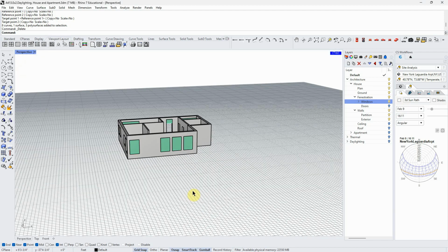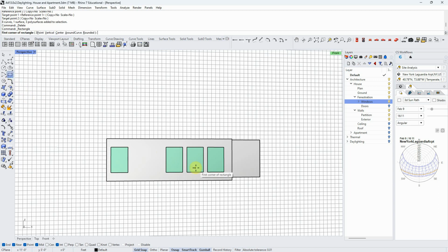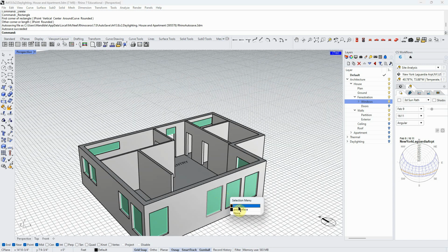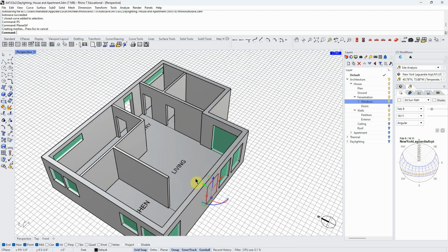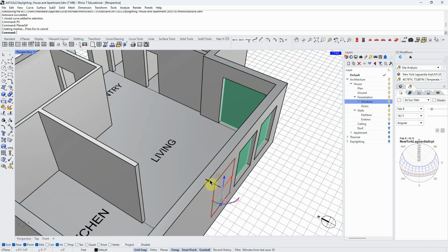The way I did that is once I had my holes, I'm just drawing surfaces on there and then moving them in a certain amount. By the way, I have polysurface as a shortcut. If you guys don't know how to make shortcuts, I can talk to you about that. They're really helpful for the things that you use often. And by the way, in the gumball, if you guys are not using it, for example, I can move this in 0.5 feet by hitting the direction I want to go, 0.5,